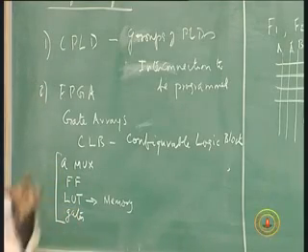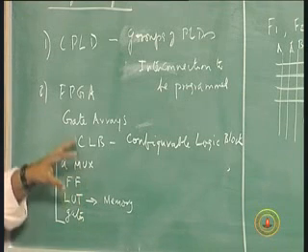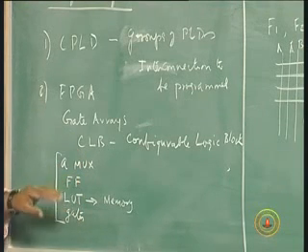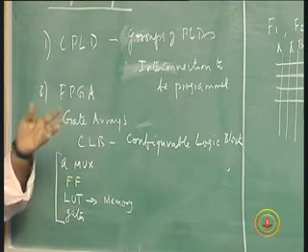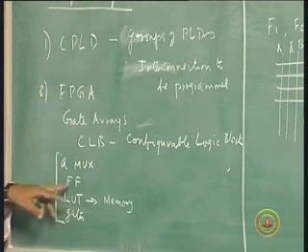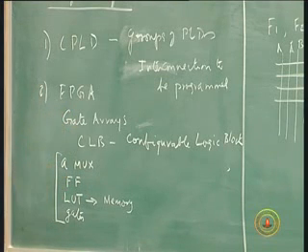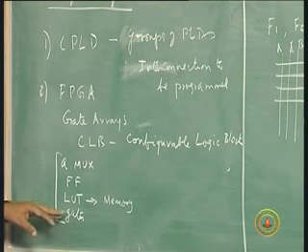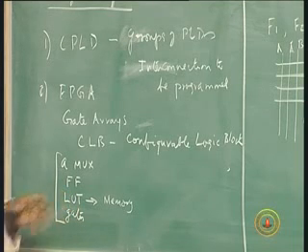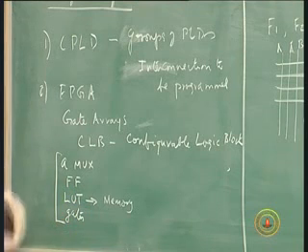And like that, several groups are there, and each of them has the same standard features. Each of them will have a single mux, maybe a 4-to-1 mux, a single flip-flop, a lookup table of a small size, 8 words or 16 words, and then a few gates, exclusive OR gates and all that. So the logic has been broken down.